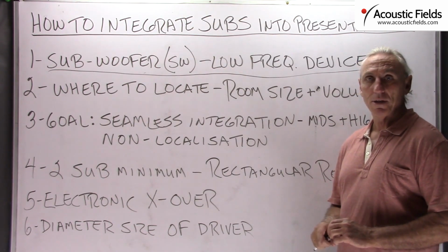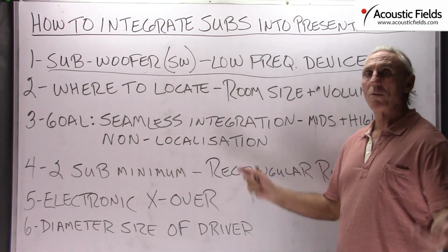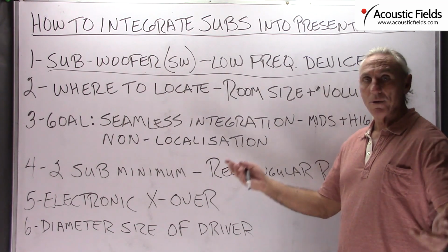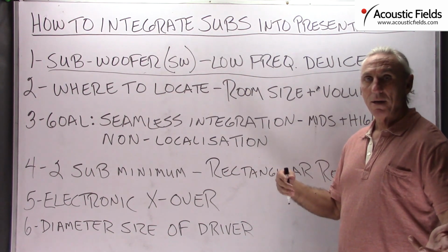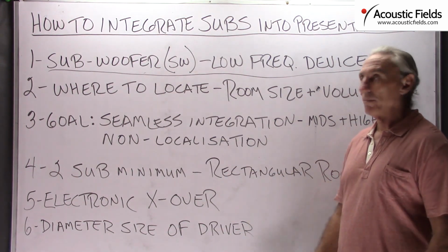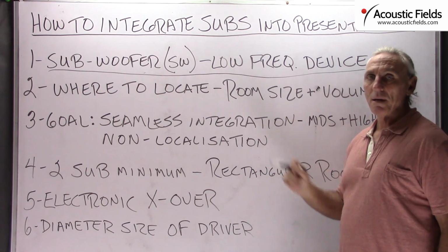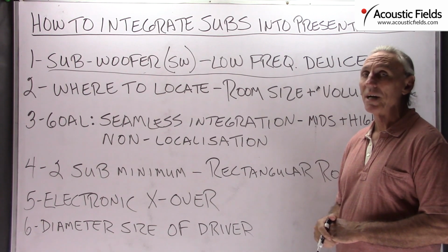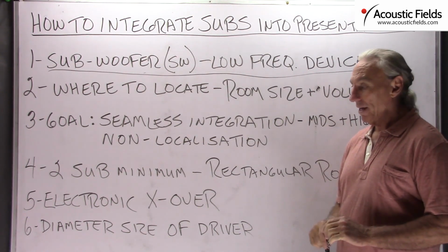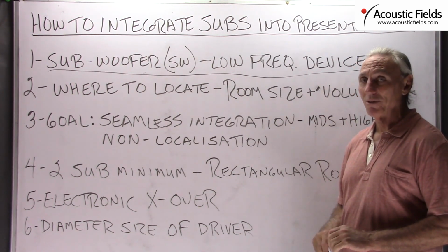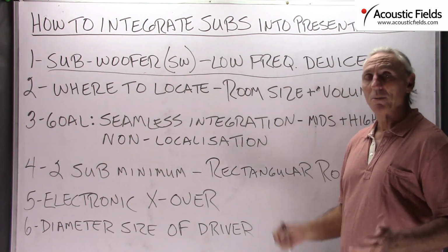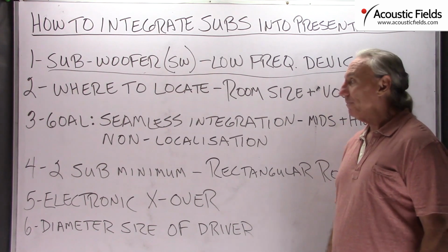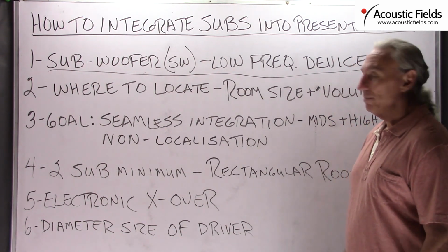People don't take this serious enough, and their rooms are just overwhelmed with low-frequency energy to the point you can't hear where the lows start, the mids begin, the highs. It's all just a jumbled mess. So start thinking about your subwoofer as a low-frequency producing device that the room does not want. It's going to do everything in its power, so to speak, to get rid of it. It's going to make noise. It's going to exhibit room modes. It's going to smear and blur everything if you don't integrate it correctly. So you have to be very, very careful here.